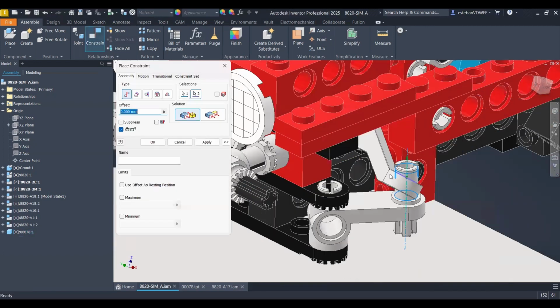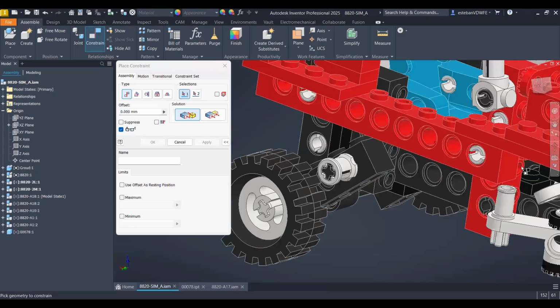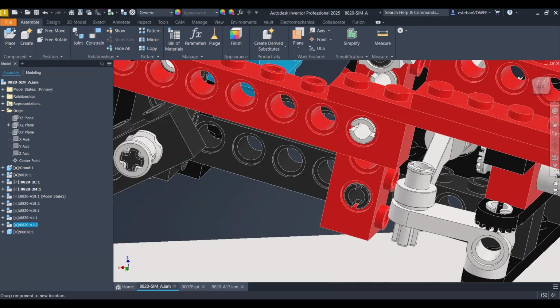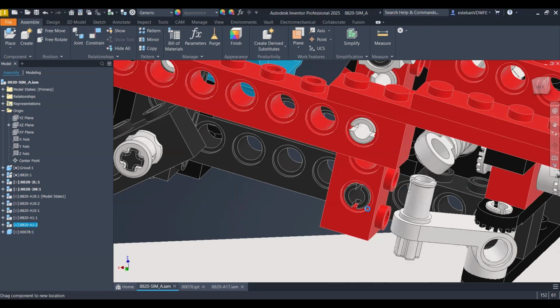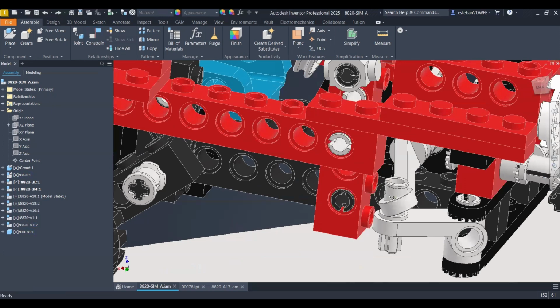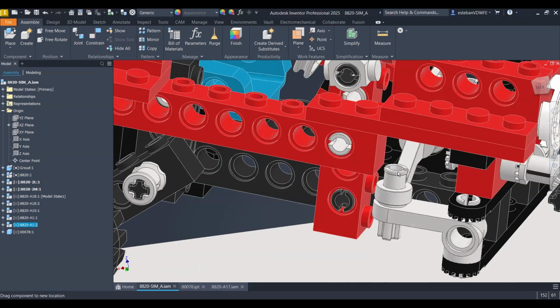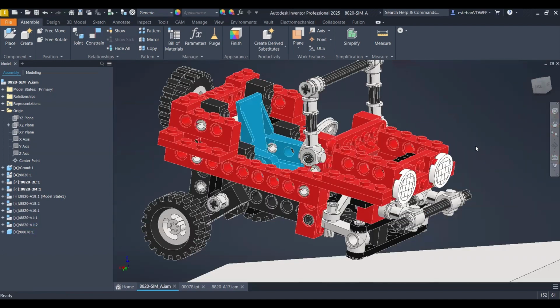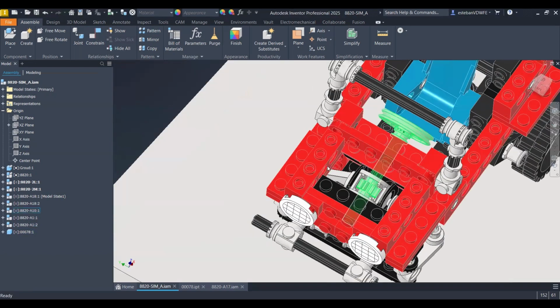Following that, we are going to make an axis and point constraint on both sides. This is because the rack requires rotating as I'm showing right now, and this is as simple as necessary, because the real life part is plastic and it flexes as it does the steering.